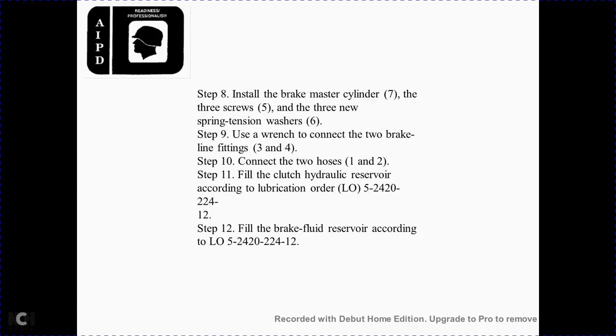Step 8, install the brake cylinder 7 with the 3 screws 5 and the 3 new spring washers 6. Step 9, with the wrench, connect the 2 brake line fittings 3 and 4. Step 10, connect the 2 hoses 1 and 2.